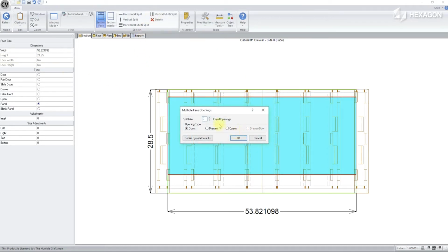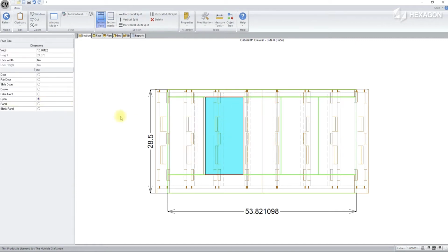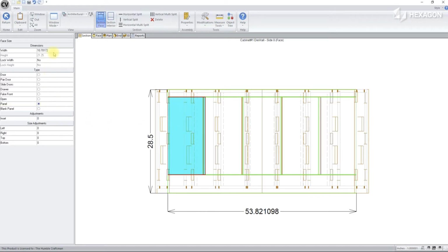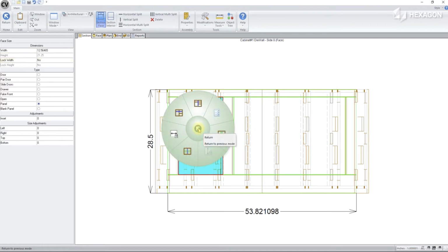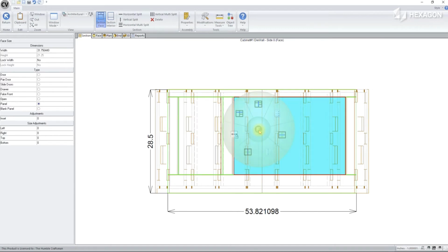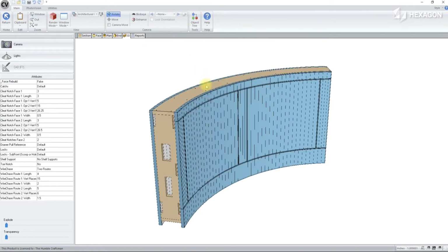The bottom panel is typically 5 inches for the 4-inch rolled toe kick, and then the remainder is the removable panel. Then I take that center section and divide that up into an odd number of panels typically, so that you can put the left panel at 3 inches for an anchor panel. You can put the center panel at 3 inches for a bracket, and you can put the right panel at 3 inches for an anchor panel. Then I space the other 2 panels out evenly, or however you need to do it. You just equal space those panels. Now you have all the panels set with their reveals.